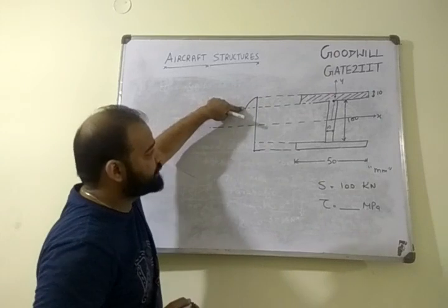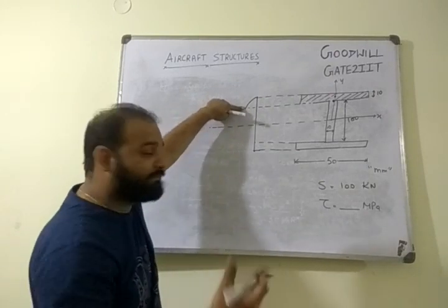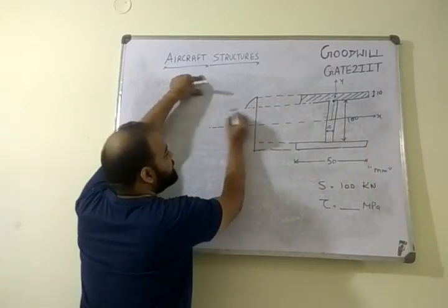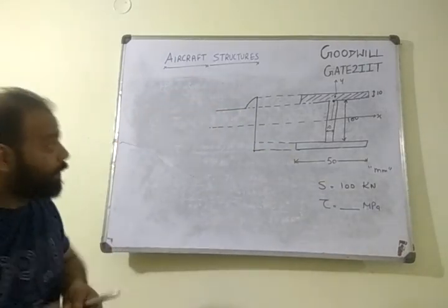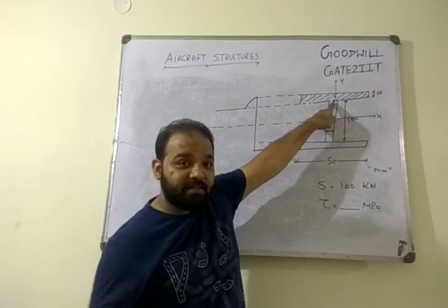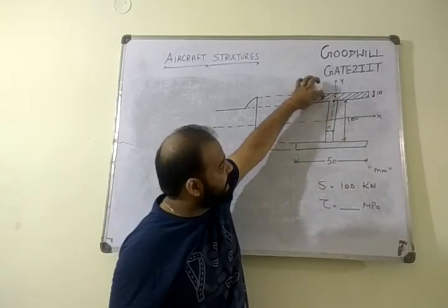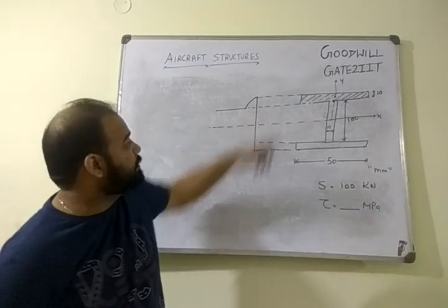You are having some value of shear stresses. You can calculate, it comes out to be some 71.1 divided by 5. You can calculate this in flange. You have calculated in web. Then what happened in web? It suddenly shoots up. Yes. Why? Because see, same shaded area, but the difference is divided by B. If you are calculating in web, it is divided by 10. If you are calculating in flange, it is divided by 50. So it is 5 times lower actually.